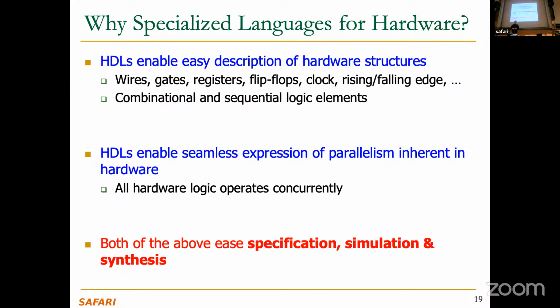That said, people have actually tried a lot to write the specification of hardware using a programming language like C, for example. I don't think that anyone has tried with Python yet, maybe. I think they have actually tried it. You can actually do that, but then synthesis becomes very difficult because you describe hardware at a very high level, as we will see also. The synthesis tools become very unoptimized because the state space that they need to search through is huge, because you really have not described what's a wire. The synthesis tool needs to figure out what's a wire, for example. So there's a lot of potential here for new techniques so that you can compile from Python or C down into gates and wires, but it's very difficult to do. And the circuits that usually end up are very unoptimized. Okay, we may get back to this because there are intermediate level languages that you can use. Python and C may be very high level, but you may actually have a hardware customized language that can enable you to do this high level synthesis.